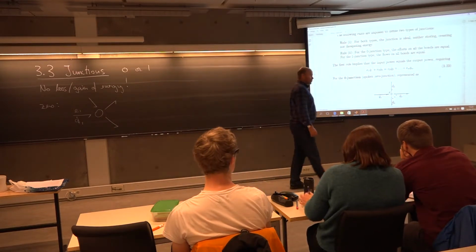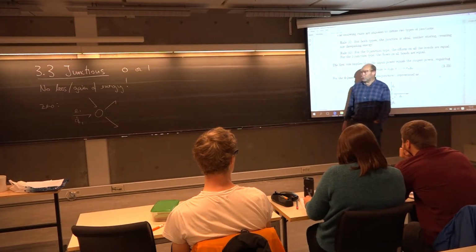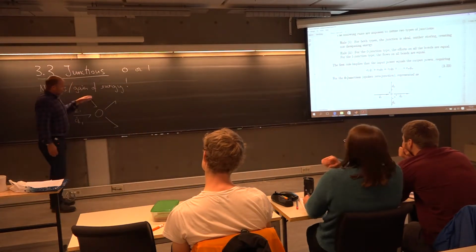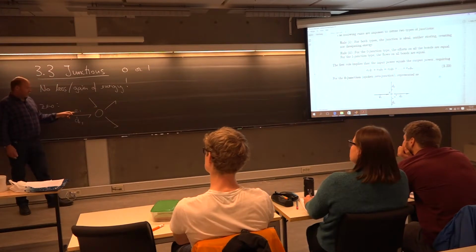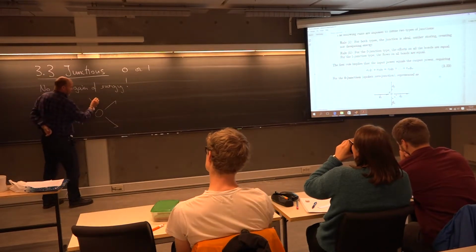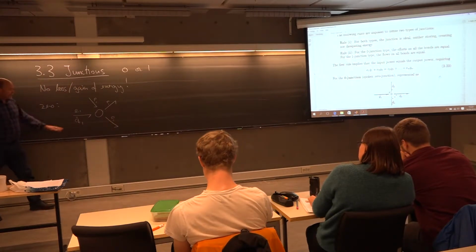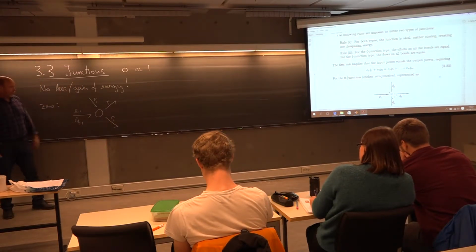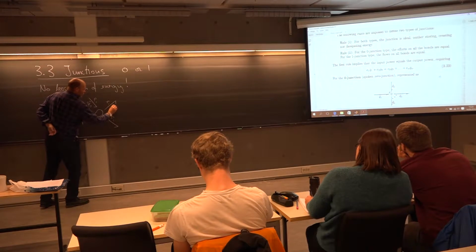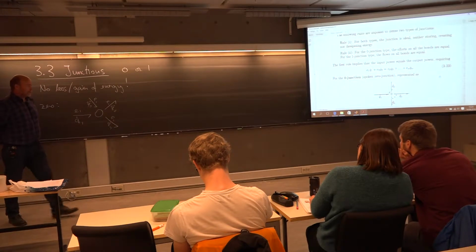But around a 0 junction, it's also called a common effort junction. That means all these bonds have the same effort. So if you call it E1, that's your choice, then it's the same effort on all these bonds. But at the junction, the flow can be whatever. If I have Q dot 1 here, then Q dot 2, Q dot 3, and Q dot 4, something like that.